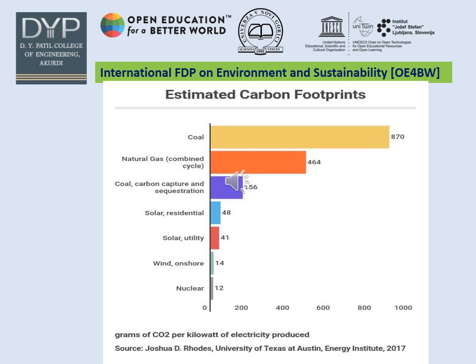To be more exact, wind energy produces around 11 grams of carbon dioxide per kilowatt-hour of electricity generated, Garvin A. Heath, a senior scientist at NREL, and colleagues concluded after reviewing the scientific literature. That's compared with about 980 grams CO2/kWh for coal and roughly 465 grams CO2/kWh for natural gas, Heath found. In other words, coal's carbon footprint is almost 90 times larger than that of wind. The footprint of natural gas is more than 40 times larger.